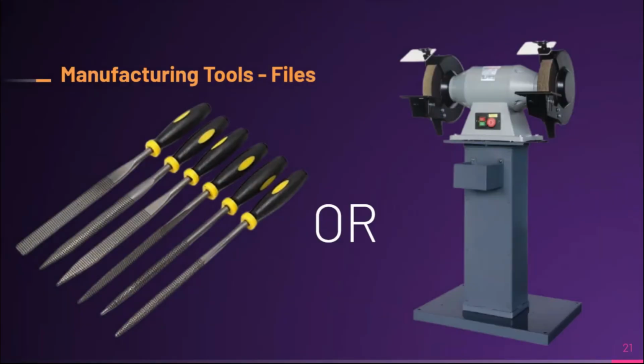The next thing you'll want is a file. Since the bandsaw will make a really rough cut, you'll want to use a file to shave off any excess material left behind. If you are very experienced, you might also be able to use a pedestal grinder to accomplish the same task.